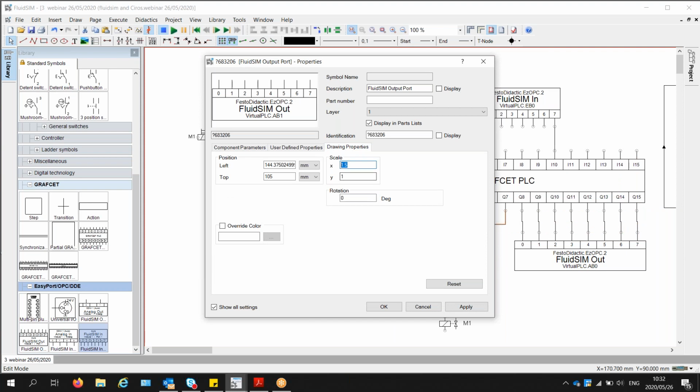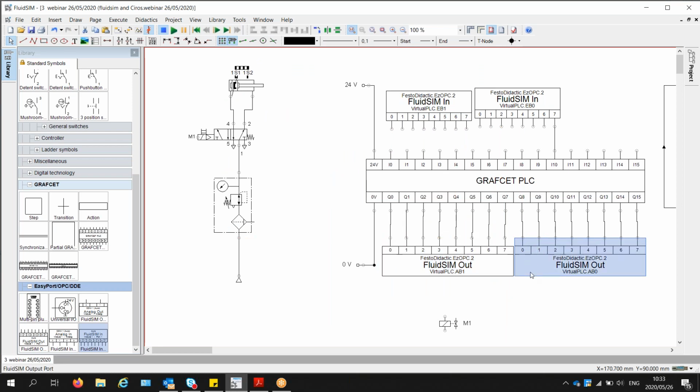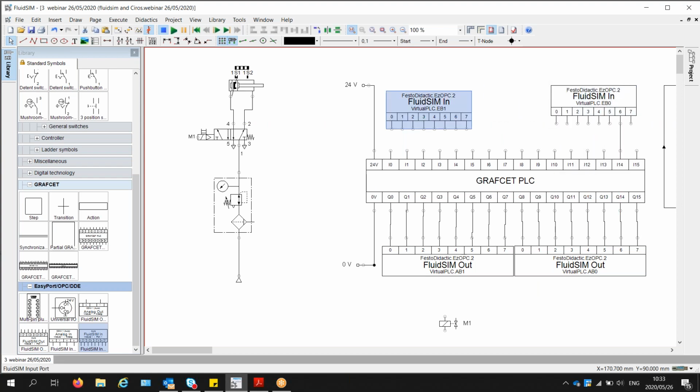And you're using 2 bytes because the MPS station requires 2 bytes. Yes, that's how many I'm using, 2 bytes of inputs and outputs, because the MPS station has the control panel, which consists of 1 byte of inputs and 1 byte of outputs, and the station itself, which has the different sensors, the conveyor module and the magazine module, which will occupy 1 byte of inputs and 1 byte of outputs. This is the reason behind this.